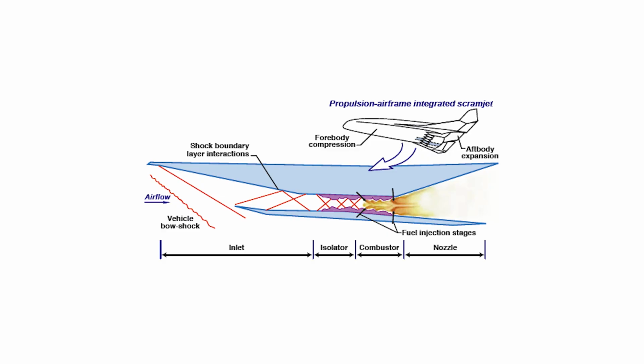Now let's learn about the scramjet engine. Scramjet, or supersonic combustion ramjet, engines present a much different situation for the combustor than conventional gas turbine engines. Scramjets are not gas turbines, as they generally have few or no moving parts. While scramjet combustors may be physically quite different from conventional combustors, they face many of the same design challenges, like fuel mixing and flame holding. However, as its name implies, a scramjet combustor must address these challenges in a supersonic flow environment.